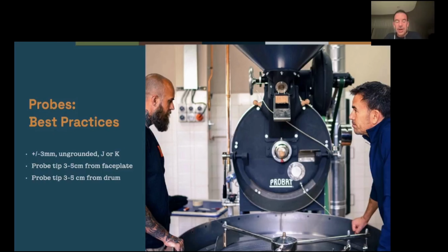And what Aillio, the company behind the Bullet, realized was they needed many infrared probe data points in order to smooth out the data. So that one infrared probe was giving a lot of volatility. So on the second machine that they built, their R2 machine, they put in 128 different infrared probes or sensors, and they fed the data from those 128 sensors into software that then averaged their readings to provide a much more stable bean temperature reading. So infrared probes can work, but you're going to need a lot more than one data point in order to take away the volatility of the reading.